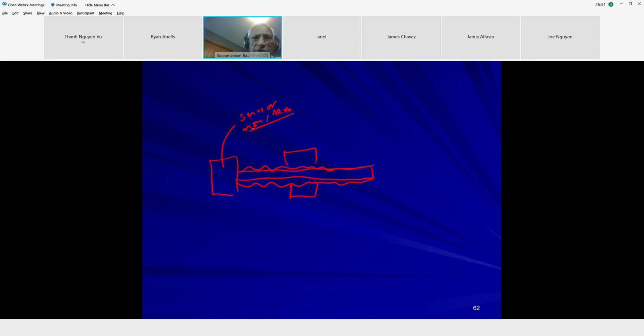Now, in the case of an electric motor, if you take a toy motor, when you apply voltage, boom, it keeps going. There is no stopping in between unless you kill the power. As a result, with the inertia kicking in, you cannot stop it at any precise position that you want. You can stop, but it would be off this way or that way by some amount, depending on how fast you're going. But if I use one of those toy motors, like a simple DC motor, and then put a stop at the end, and this is automatically the stop. When I power it, it'll keep moving all the way and hit this end stop, and it can't go anywhere else.